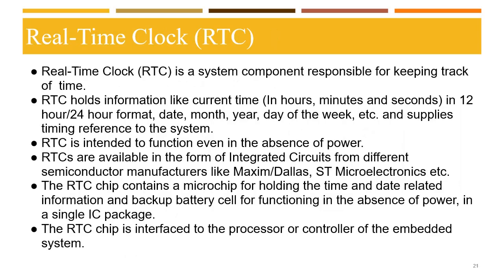Real-time clock (RTC) is a system component which is responsible for keeping track of time. RTC holds information like current time in 12 hours or 24 hours format, date, month, year, day of the week, etc., and supplies timing reference to the system. RTC is mainly intended to function even in the absence of power. RTCs are available in the form of IC from different semiconductor manufacturers like Maxim Dallas, ST Microelectronics, etc.